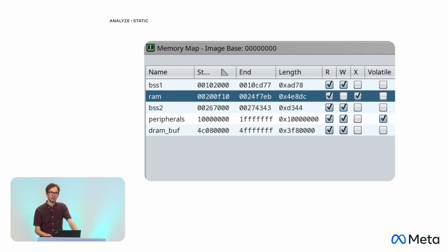When you want to do something, when you want to print a character to the screen or draw something or make a sound, you make a syscall. So you call into the operating system and you say, hey, Linux kernel, I want to do something, and then the Linux kernel goes and does its magic. But when you're running bare metal code, like most firmware is, when there's no operating system, there are also no syscalls. There's nothing to call to say, hey, I want to write a character out the serial port, for example. So how do you do it? In most modern chips, it's actually done just using memory, reads and writes just like anything else.